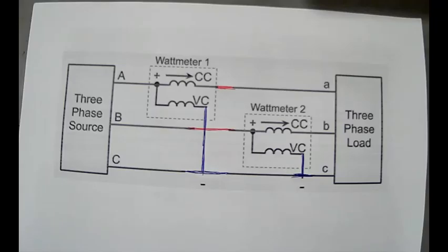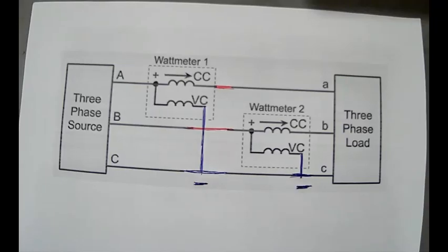Okay, simple like that. And those are the negative sides of the wattmeter. Notice that the positive sides were there, the negative sides will now be connected there. Right, do study how to connect 2 wattmeters to 3 phases. Very important. And how to draw the diagram.